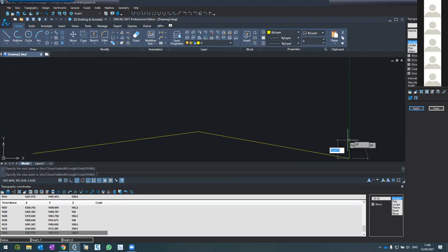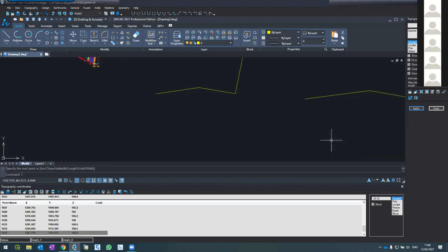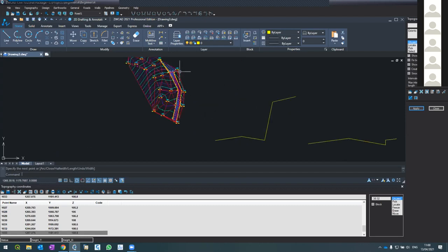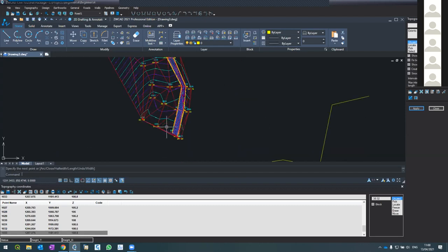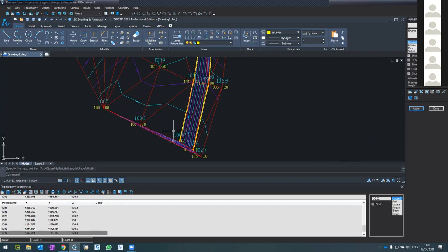Here, usually what we have is the sidewalk. Right? This is the sidewalk. It's only 15 cm or 20 cm, depends. 20, 25 cm. But also, if we don't mark this, it will give us problems. It will give us wrong contour lines. Guys, I want you to try and practice this. It's more complicated, but it's very important.